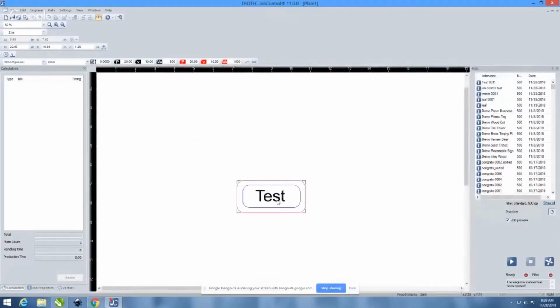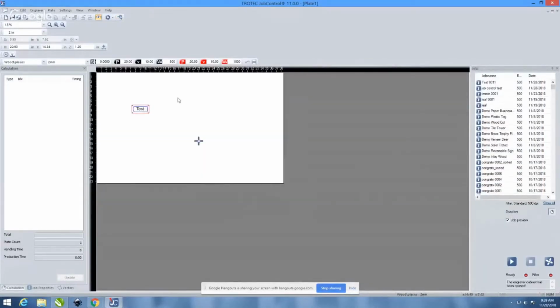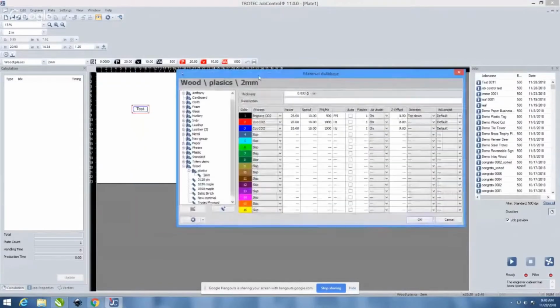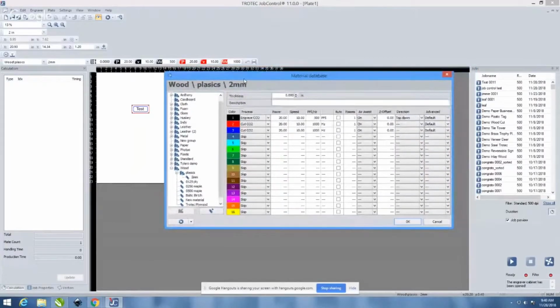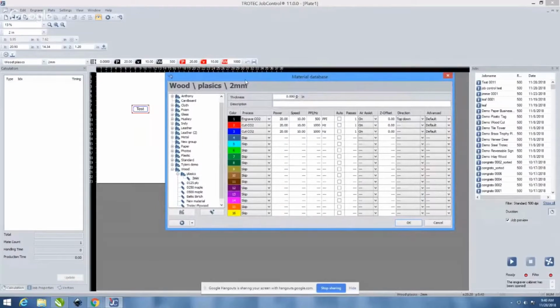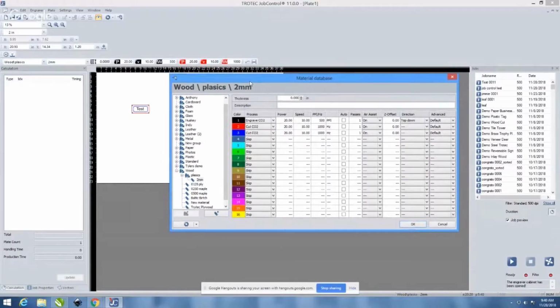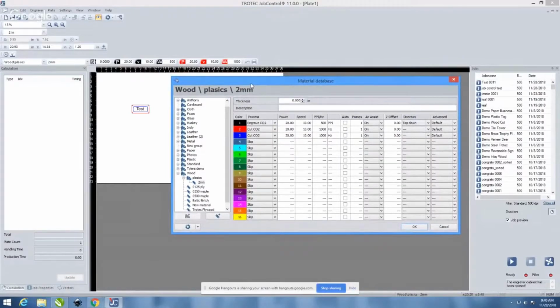And now we can see our blue line here. I should also quickly mention a lot of issues I had when I first started using the laser. When I did the cuts, I kept forgetting to put the line as the thinnest line. So in Corel, it's a hairline, and in Illustrator, it's 0.01, I believe. Is it 0.01 or 0.1, Anthony? I can't remember. 0.01. When in doubt, just go smaller.